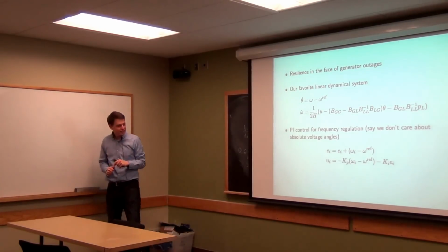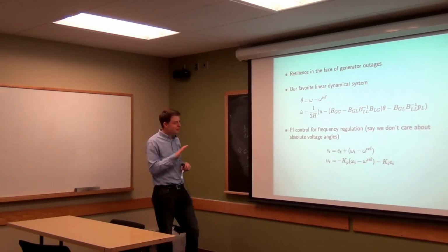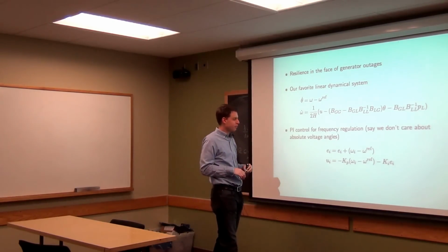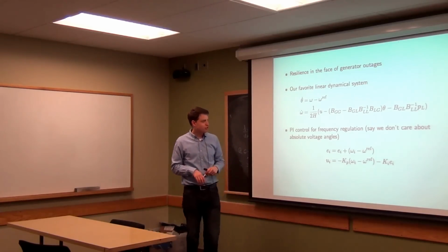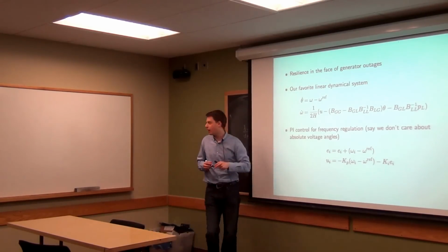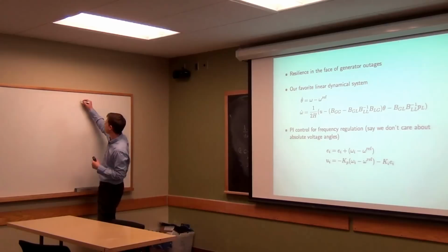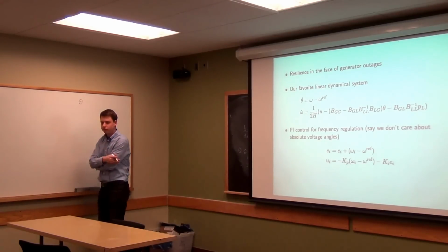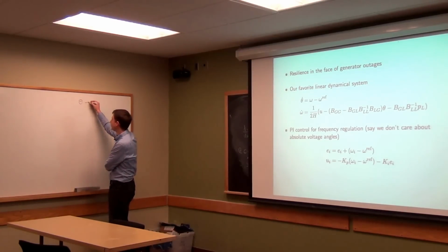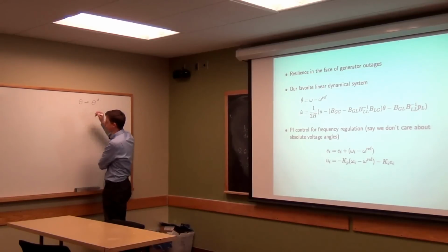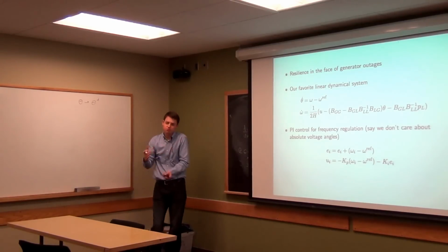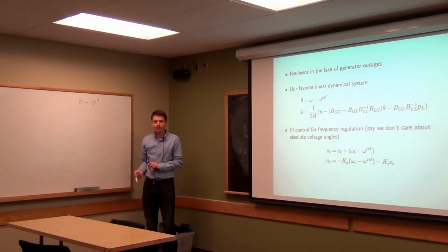Because I almost beat it to death, so hopefully that rings a bell. And let's talk about a slightly different setting than we had before. Let's talk about just frequency regulation. So before, in our system, we wanted to get the voltage angles to some desired quantities, right? We wanted to make them some desired numbers because that would make power flow the correct way, essentially.